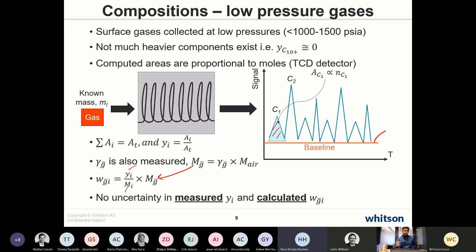Because you have the instrument uncertainty when you do the analysis on the component. So you cannot say there's no uncertainty. Of course, there's uncertainty because the gas chromatograph has some uncertainty limits. This is based on ASTM standards, that if you run a sample, you know that this component with that kind of concentration has an uncertainty of plus or minus some amount.